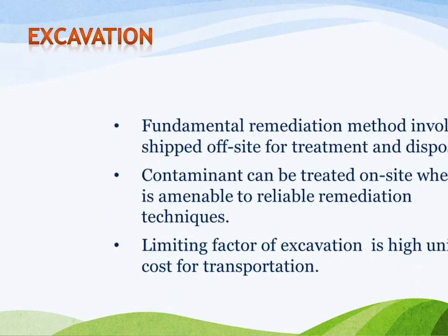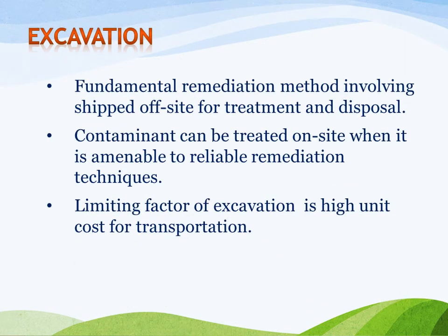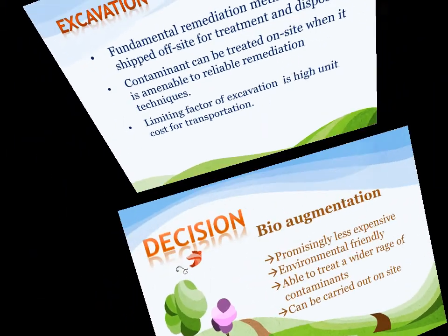Excavation is the most fundamental remediation method, involving shipping off-site for treatment and disposal. Contaminated soil can be treated on-site when it is amenable to reliable remediation techniques. The limiting factor of excavation is the high unit cost for transportation.